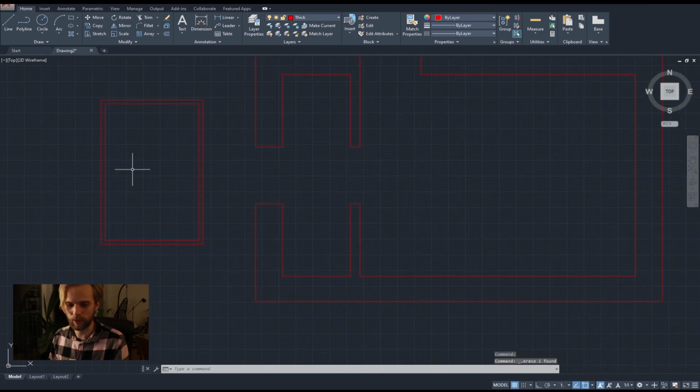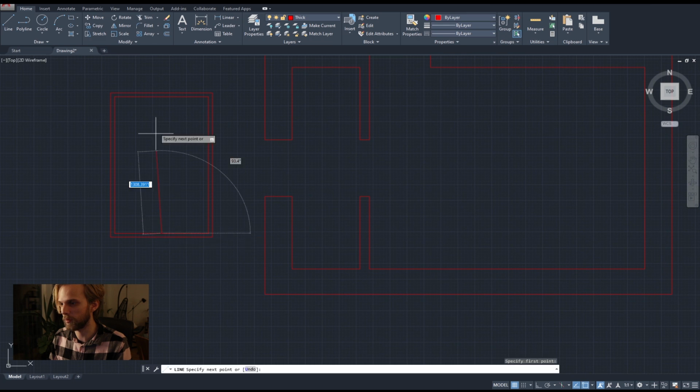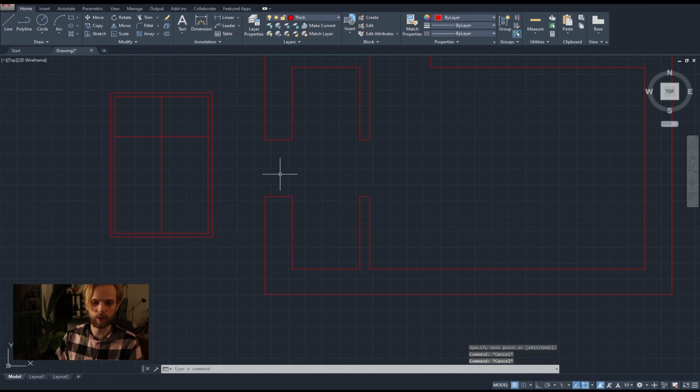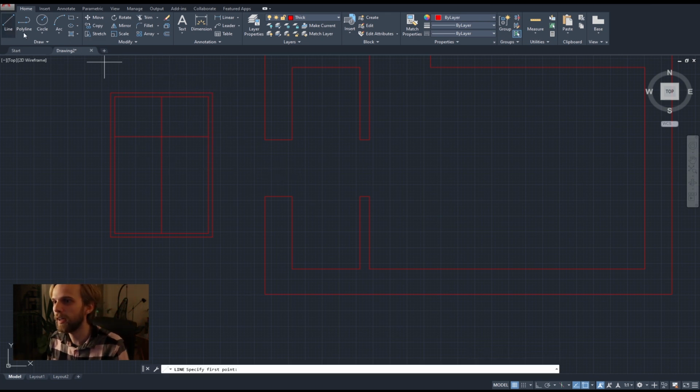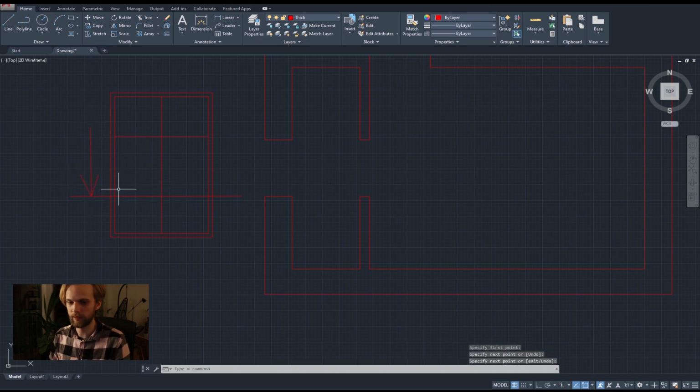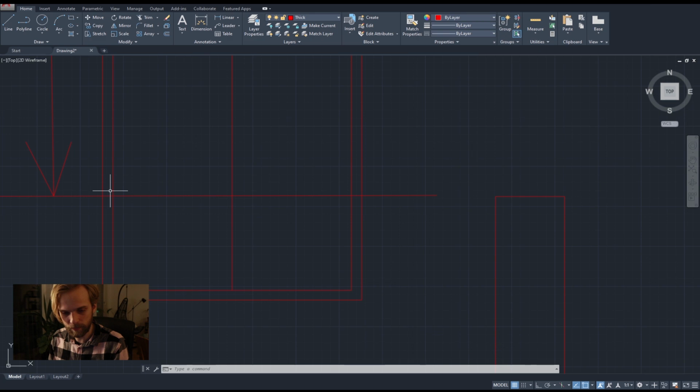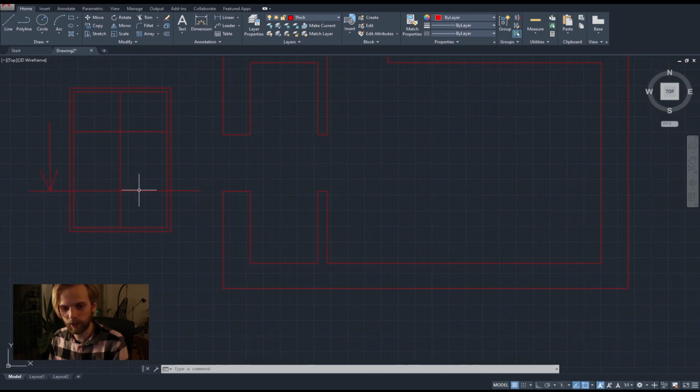So let's say I have a window that has some sort of partitioning, whatever. It's just a window, right? In the facade, and I am cutting through that window, like so, at this height, and I'm looking at the cut straight downwards. That means that I will see the frame. I will be cutting through the frame, the glass, frame again, and then wall, right? So wall, frame, glass, frame, wall.